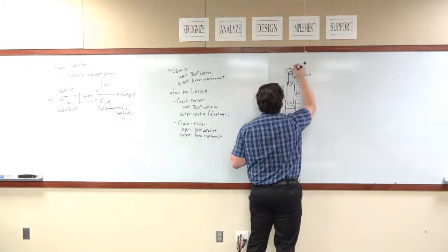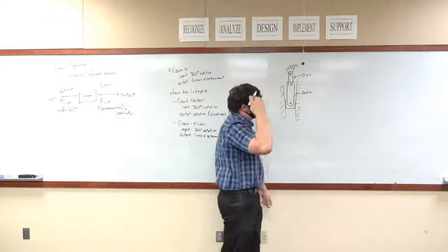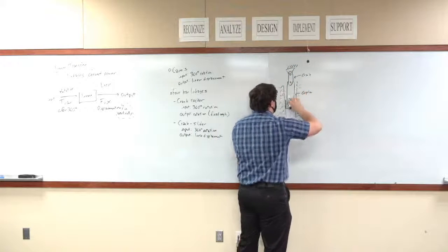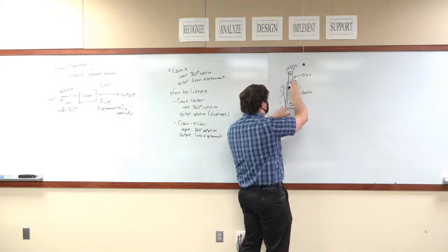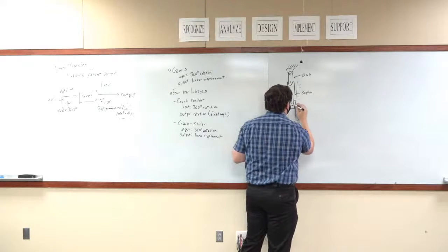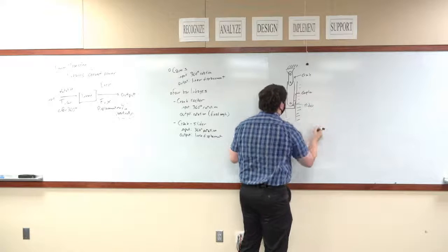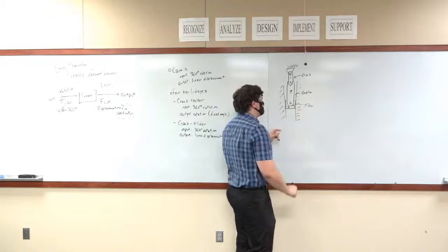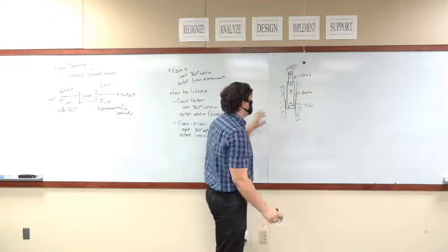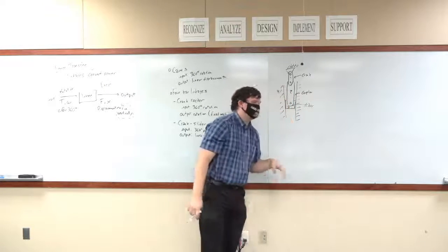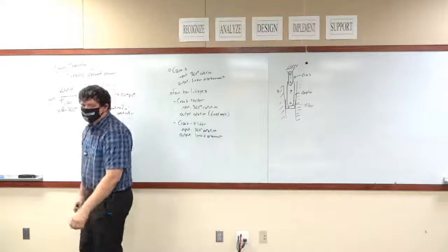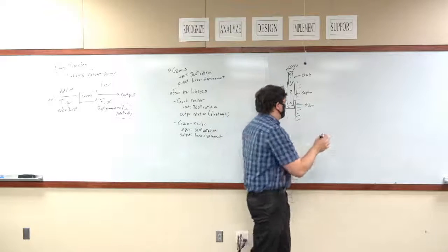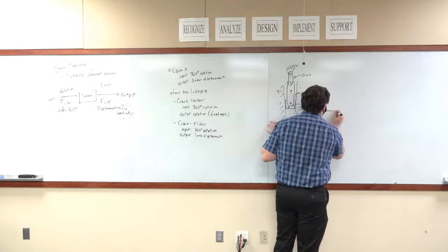And this also is rigidly connected to ground, okay? Now, as this crank rotates upward and downward, the coupler acts as a liaison between the crank and this slider mechanism, okay? This is your link number 1, this is your link number 2, this slider is your link number 3, and the ground is your link number 4, okay?